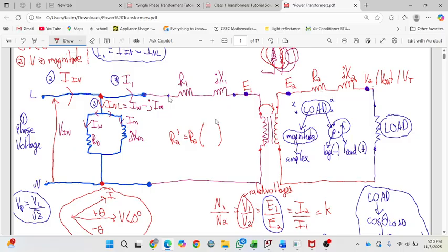So the factor is basically just your turns ratio squared in the correct formation. The trick is if you're going towards the primary side, which is the N1 side, the N1 will be on top and the N2 will be at the bottom, and it's squared. So that will give you the secondary impedance or the secondary real part on the primary side. The value itself will change because of the turns ratio. Same equation if you wanted to find the X2 prime, it would just be X2 here, and the turns ratio part will be the same.